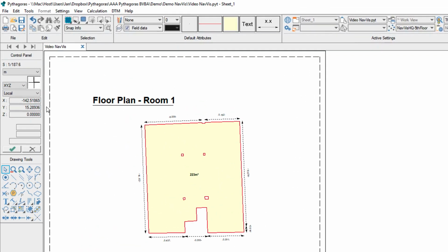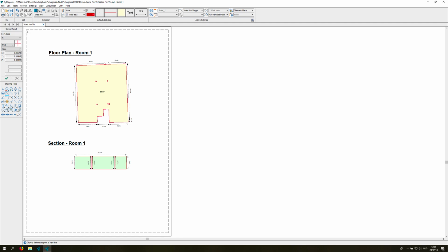The last step is creating the actual layout by switching from local coordinate system to the page coordinate system. So everything we draw in the page coordinate system will be linked to the page or to the sheet. So first of all, we draw the borders of the layout using normal lines.